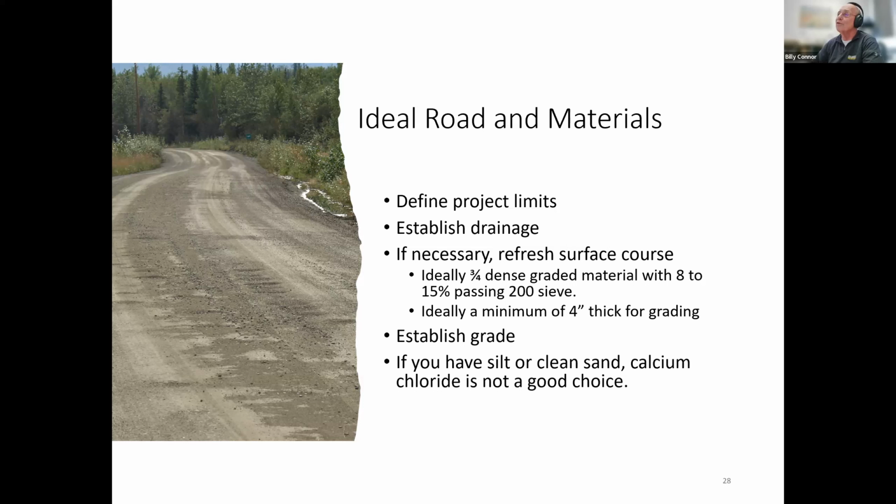What you don't want is to have your roadway not have drainage, and the water sit on the road, or a situation where whenever it rains, you are ponding water. So you want to be able to get the water away from the road. And that's whether you're using palliatives or not. Even on a paved road, the old adage is the first dollar you spend on a roadway should be on drainage. If necessary, we might want to refresh our surface course.